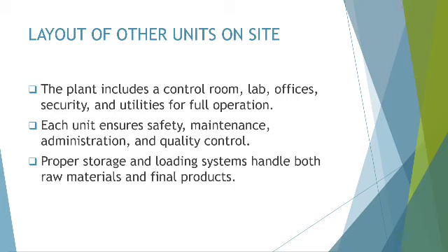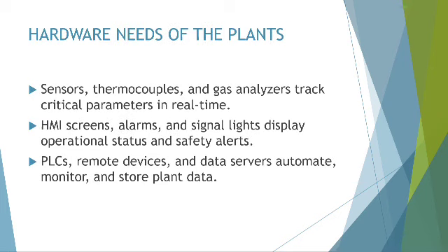And moving on to the hardware part of the plant. For the plant to run reliably, hardware is critical. We use sensors and thermocouples to monitor temperature, pressure, and flow in real time. Gas analyzers help us detect leaks or impurities, ensuring safety and compliance.